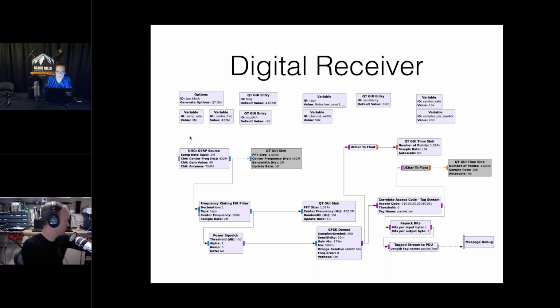Now, the number and types of antennas out there is essentially infinite. You can get something like this, an LTE antenna that has multiple elements in here so that it can receive and transmit at the lower 700 to 900 band, as well as the higher multi-gigahertz band. These aren't that much either. I think this was $10. So it's not a bad idea, if you're going to work in this area, to just build a little kit with 5 or 10 antennas in it. And they don't cost that much.